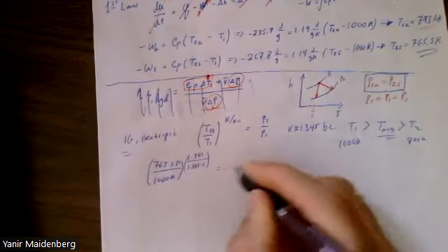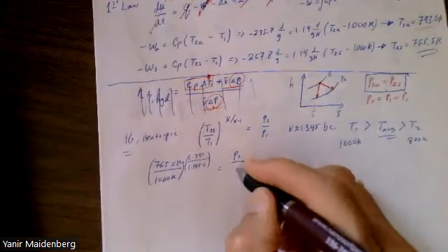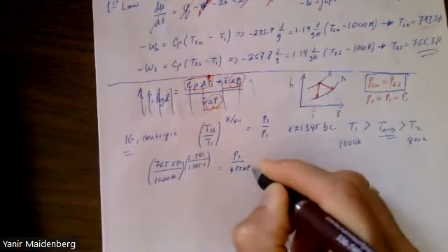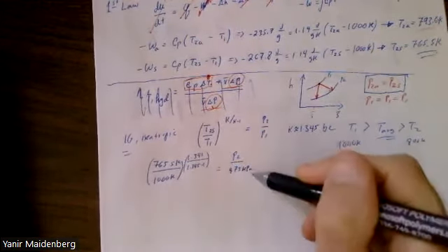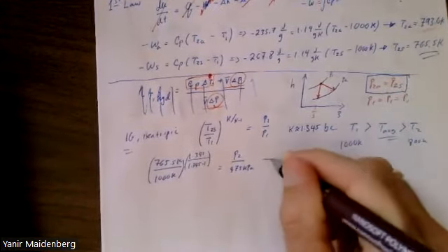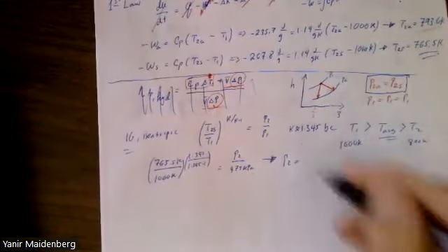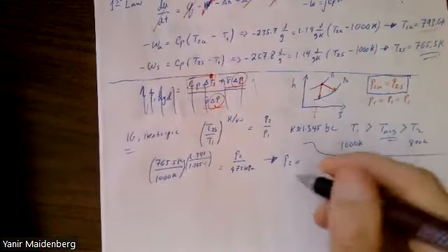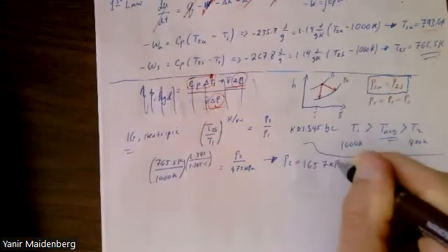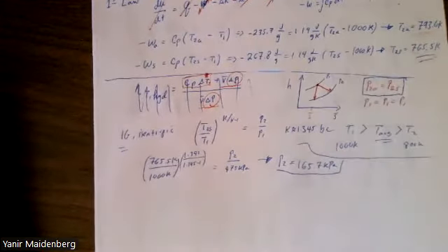And it's going to be equal to P2 divided by P1. Okay, and so I don't have to convert this to SI or to whatever. Whatever the pressure is for P1, it will be for P2 because this is the ratio between them. Solve that for P2, and you get that P2, whether it's the isentropic condition or not, is going to be 165.7 kilopascal, which from the Mollier diagram, you can see it does go down, makes sense.